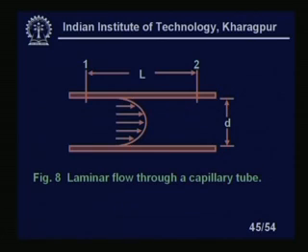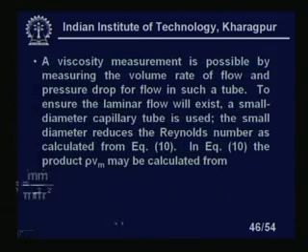You see here the velocity distribution of the laminar flow. The liquid is in contact with the inside pipe diameter, there is no motion there, and here you will find the velocity is maximum, okay, at the central point. As it goes toward the walls, there will be no movement of the liquid which is in contact with the inner surface of the pipe. So, this is the velocity profile of a laminar flow of a liquid inside a pipe, right. We are talking of Vm, that is the average velocity, taking measurements at separate points and averaging.